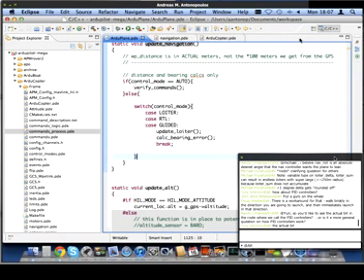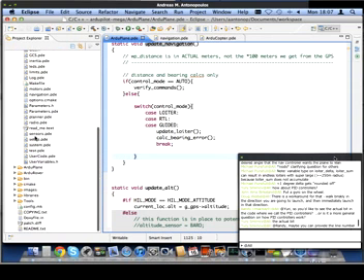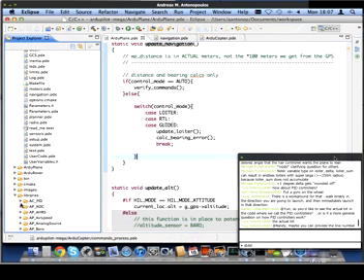So in order to keep yourself just above the stall speed, you first of all need a mission command that sets your target airspeed. You'll find in the set of mission commands a special command that sets the target airspeed, and you typically want to set it to a little bit above your stall speed, say your stall speed plus 30 or 40%. ArduPlane will then try to keep your airspeed at that target speed, and it will try to lower your altitude slowly towards the landing point.